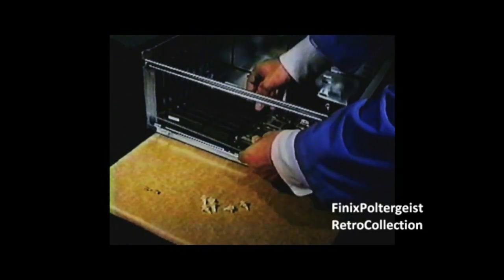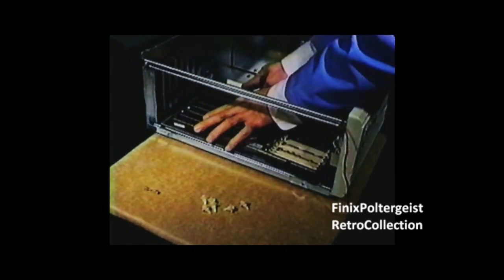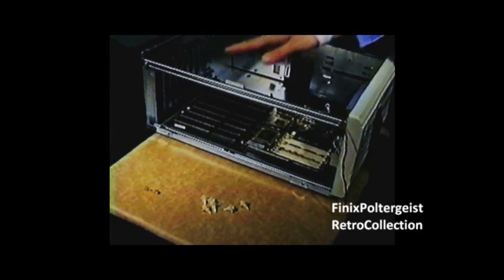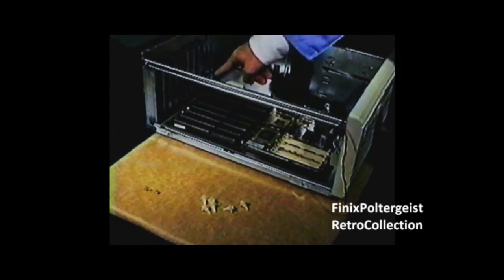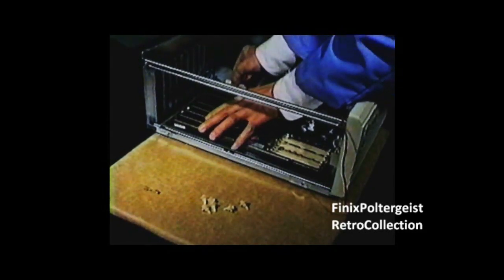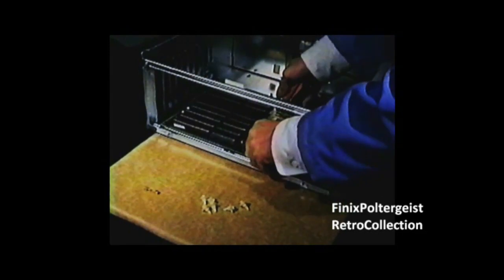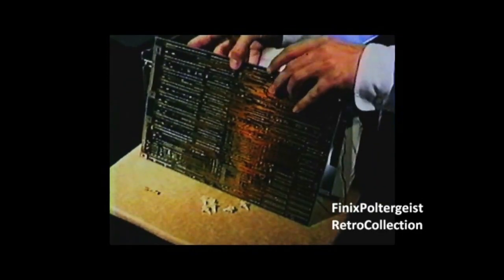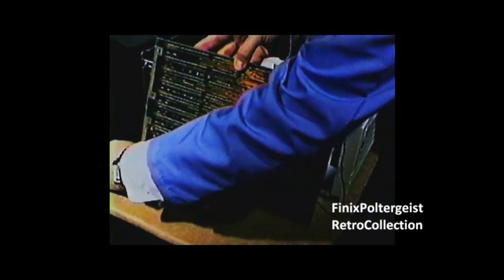First, align the motherboard with the holes in the case to determine which holes will align properly. Remember to orient the board so that the expansion slots are closest to the rear of the case and the keyboard socket is aligned with the appropriate opening in the case. Then snap the white plastic insulator into the preformed holes in the motherboard. As a minimum, each corner should be supported with an insulator.